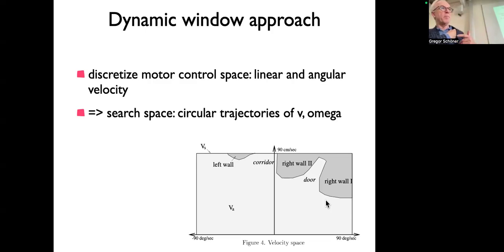And so you have to have some model of that. It's like a model of how well you can brake. So it's an ad hoc model. We have a lookup table where, with this speed, at that distance, I can stop in front of me. What is the distance I need to brake? So based on that, you can compute this configuration space representation in velocity space.